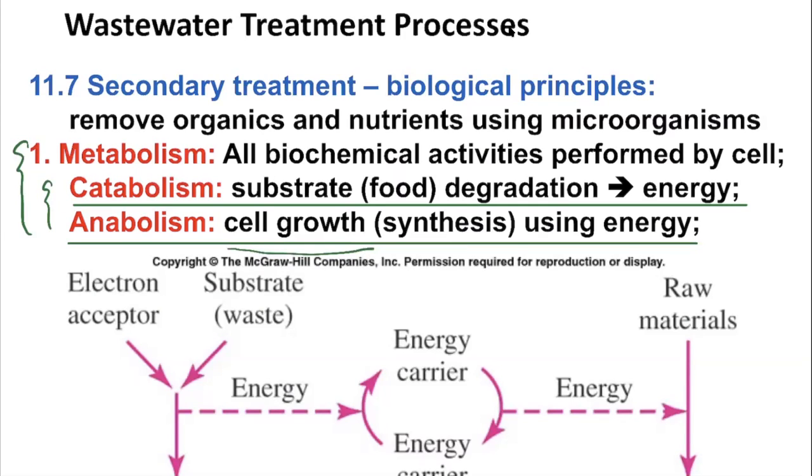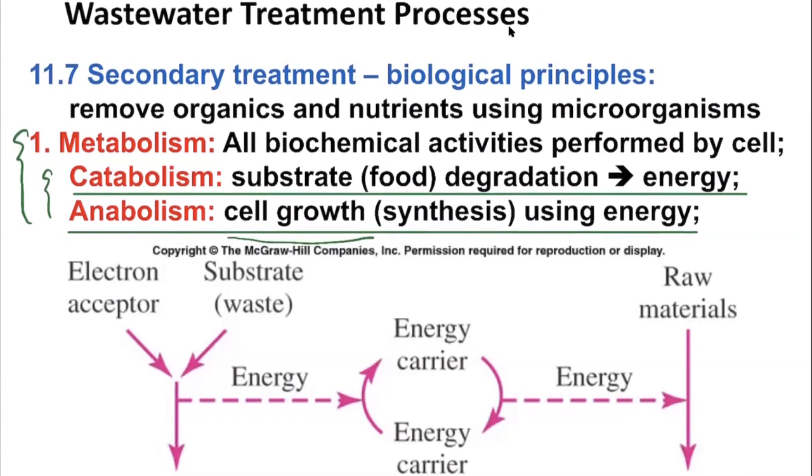So because of that, the aeration tank or the activated sludge process is going to use these 2 processes, and people have to design or find the bacteria that can balance between these 2, right? Because on the one hand, the catabolism is quite important because it determines how much food the bacteria is consuming. But at the same time, we want these bacteria to propagate themselves, to grow more cells, so that we don't need to pay a lot in terms of transporting these bacteria, right?